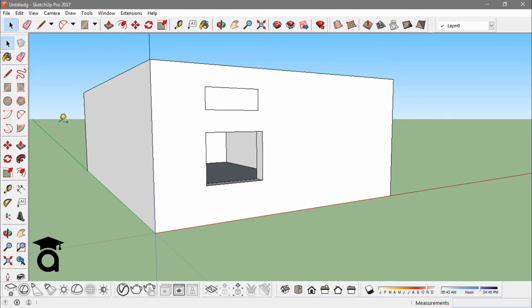One thing you notice when you go into the tape tool is that it shows this plus sign at the bottom. What this means is whenever I click an edge, it always makes these guides. If I hit the Control key, now this plus sign is off. It means it will not create that guide, rather it will only give us the length.